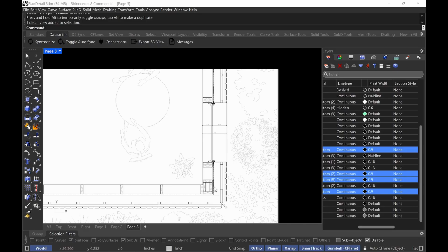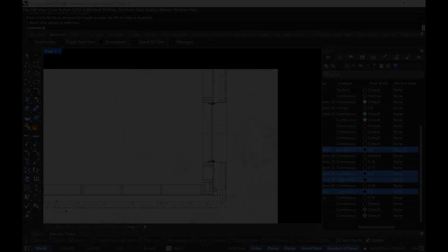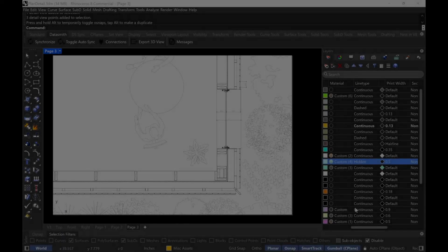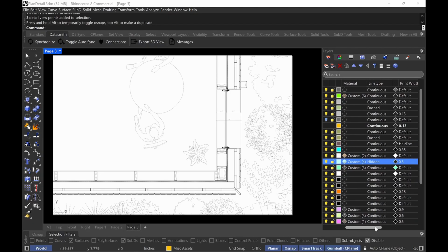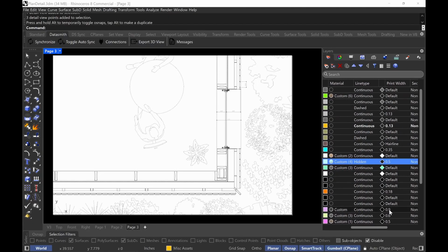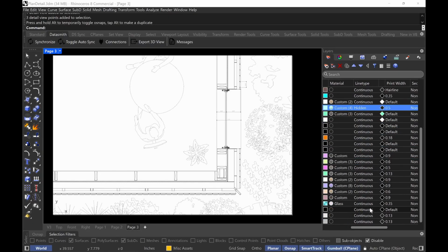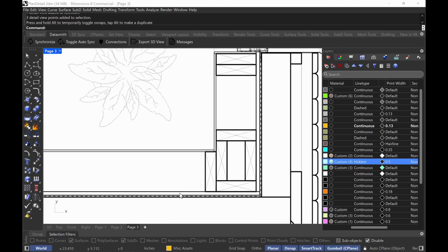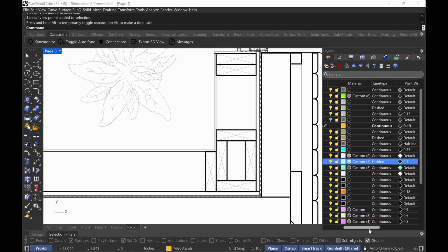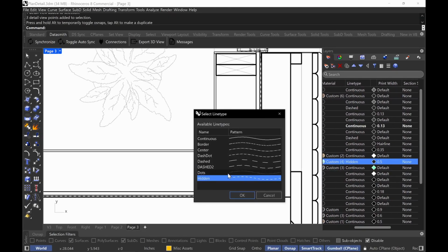Yeah. So I might fast forward through this just so that I can set up more line weights, but I just want you to understand that's what I'm doing basically. So I finished assigning line weights and line types. If you move to the side, you can see all of the line types and line weights that I've assigned. Most of them are continuous lines. There's only one dash line, and that's the membrane that you see here. I'm using it right here. You see this membrane? If you go here, I have a membrane layer right there. I made it a hidden line.